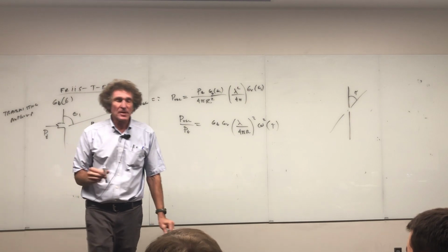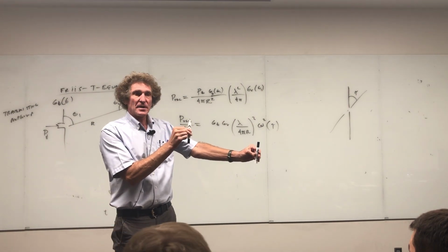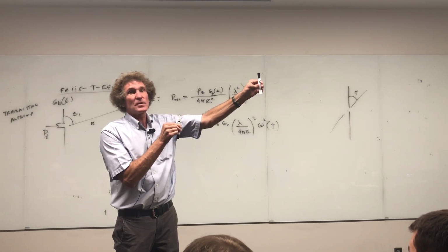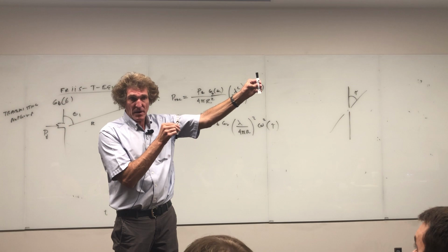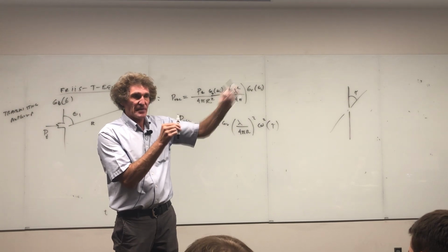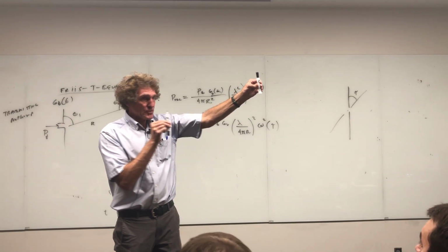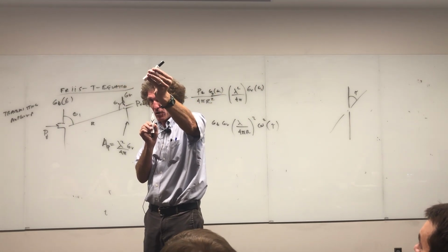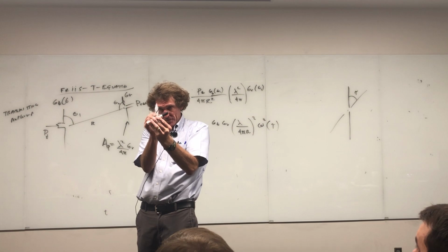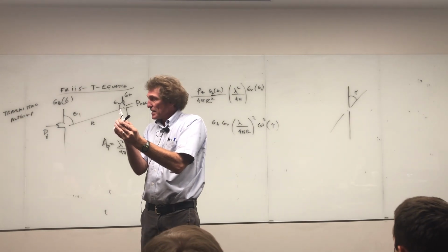Now here's a little bit more complicated thing. I want you to follow me. If I have two antennas like this, and I take one and I skew it upwards, remember they're still aligned vertically, right? Now the gain of this one and the gain of this one isn't going to be max gain. Both of them are going to be dropped down, right? By the cosine, or it depends what it is. If it's short dipoles, by the sine squared of the angle between the vertical direction of the antenna and the radius vector r, right? Now if I take these two and then I tilt one like this, now you've also got to adjust for the cosine squared of the angle of tilt, all right? It would be the angular difference between the vertical and this angle right there. Follow me on this one, class? Everybody see that?